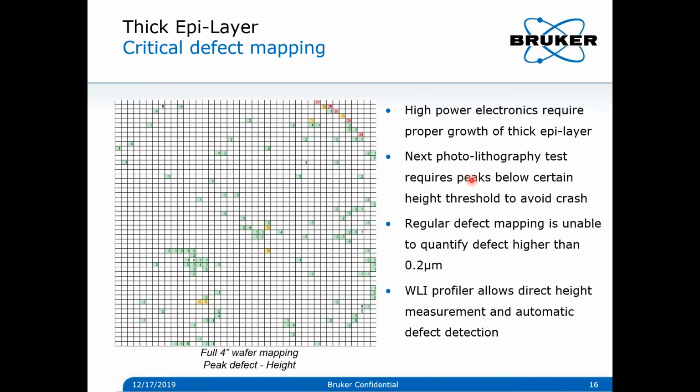This defect can protrude out from the wafer in a way that it will start to be hazardous for the next step, which is the photolithography. You may damage the photolithography system. And of course, you don't want to grow further those epi layers if they are already bad, otherwise you will lose a 1-week production slot.